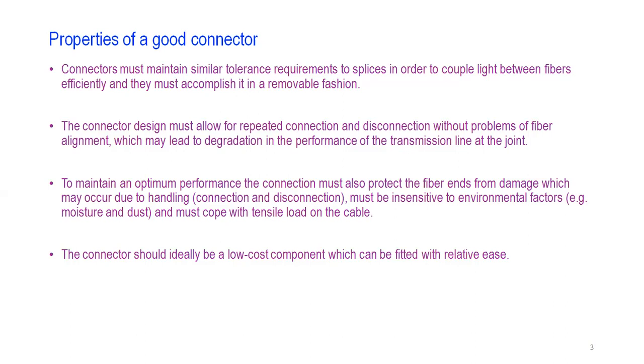Connectors must be insensitive to environmental factors. What are the environmental factors that we are discussing? Moisture and dust. If moisture or dust enters into the optical fiber cable, then the light wave is going to get scattered. It's going to result in losses. So connectors should protect the optical fiber from environmental factors too, and must cope with tensile load on the cable.